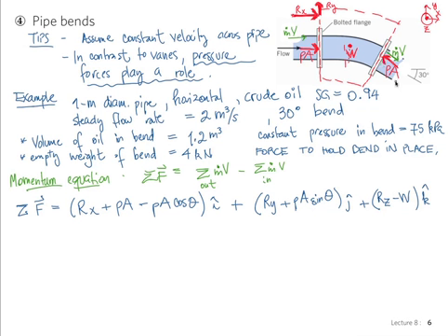The fluid on the other side of the pipe that I've cut out of my picture when I drew this box, which is my control volume, is pushing on that area. It's not pulling. It couldn't possibly do that. Always pressure acts normal to every surface. I just sort of mechanically drew the arrow in the wrong direction because the momentum does point that way, but it was a mistake.